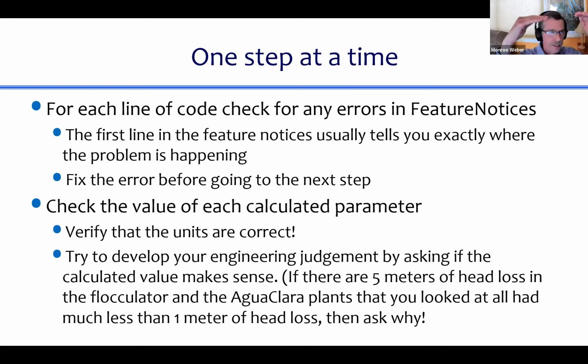There's notices in FeatureScript of all the errors that are showing up. And if you keep on going, you're just going to get this accumulation of errors, and it's going to be confusing. And Izumi can vouch for this. You just get buried in errors. So what you want to do is, the first time you get an error, stop right there. And usually the very first line in the error report, the first line that has the line number and position number of the error, that's what you want to click on, and it'll take you right to your FeatureScript code to where the problem is.